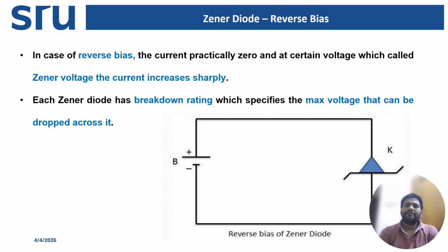So what happened? A Zener diode is special, unlike a normal diode. A Zener diode has a heavily doped design with a thin depletion region, manufactured to have a precise breakdown voltage. This breakdown voltage is called the Zener voltage, denoted by Vz.